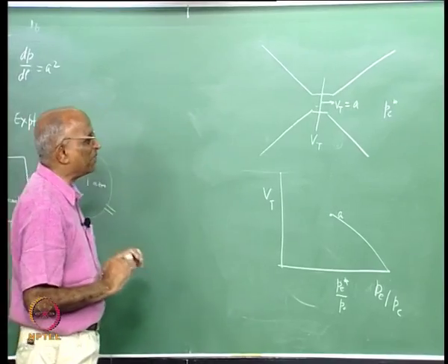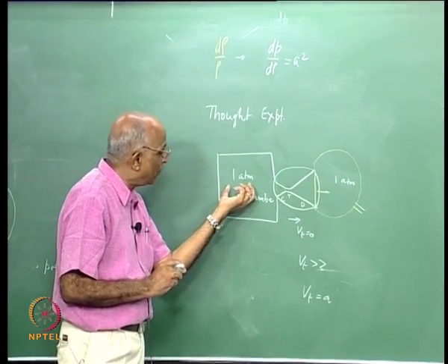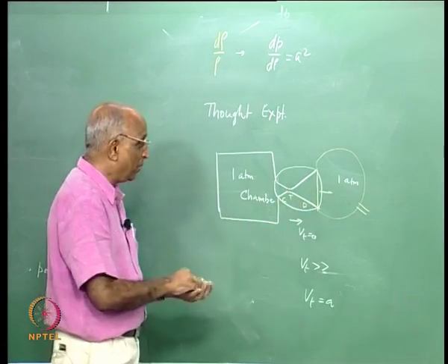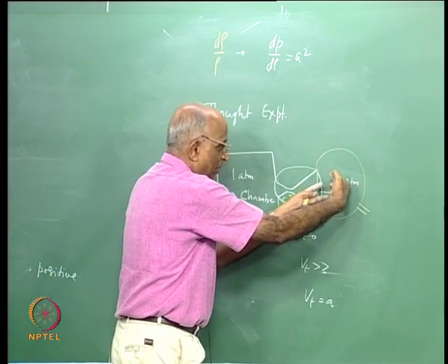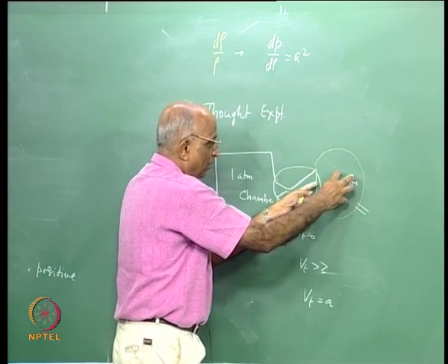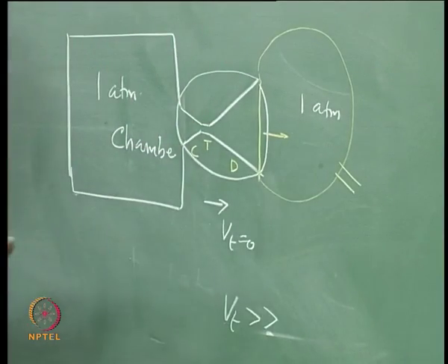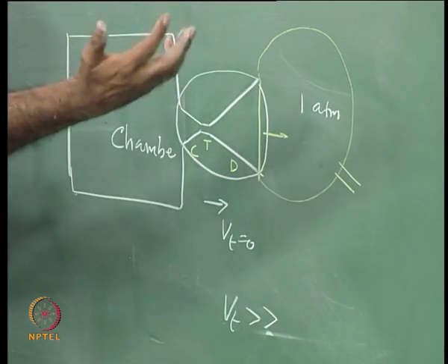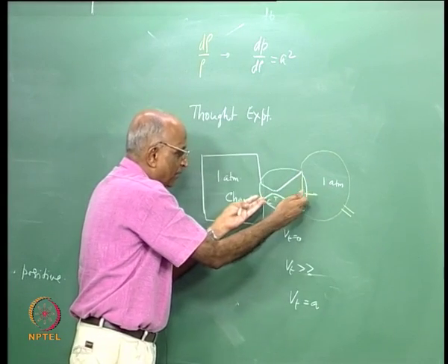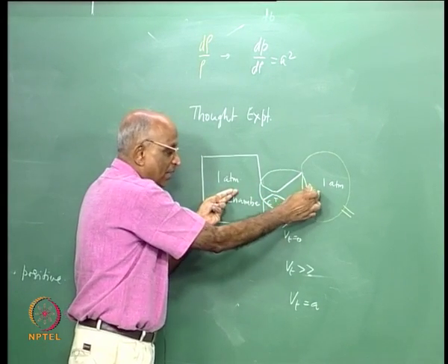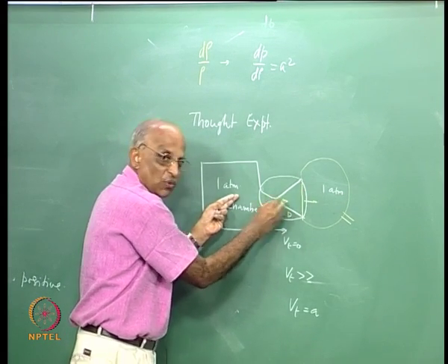Now, let us ask ourselves some foolish questions. Why does the mass flow from this chamber to the outside? Because I suck something. When I suck something, I reduce the pressure here, and this information of a reduced pressure is transmitted through this over here, and that is why mass flows. I suck something, the information reaches there, and that is why something is flowing. Therefore, as I keep on decreasing the pressure, the tank senses that information about the downstream pressure being lower, and therefore the mass flows.